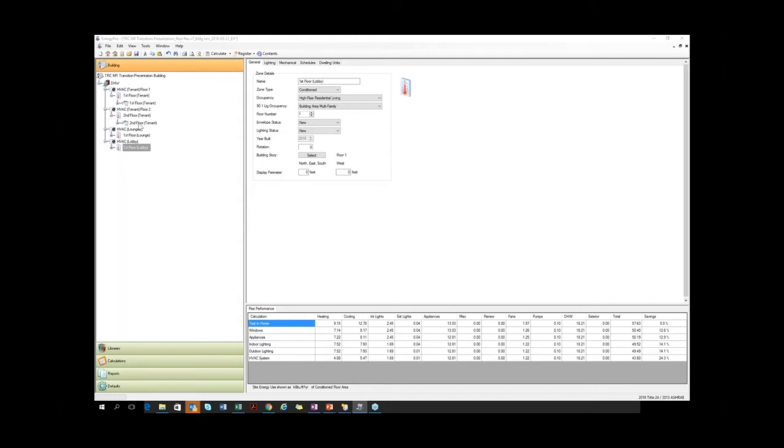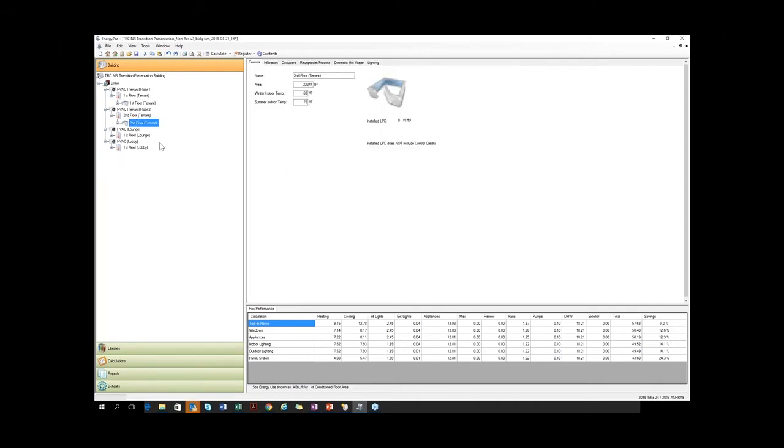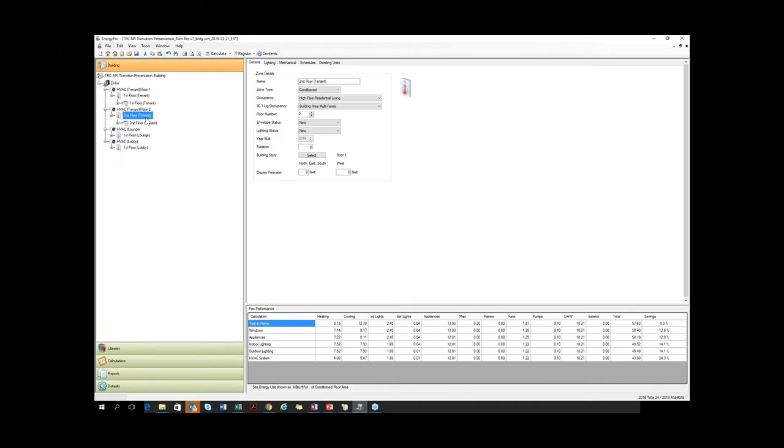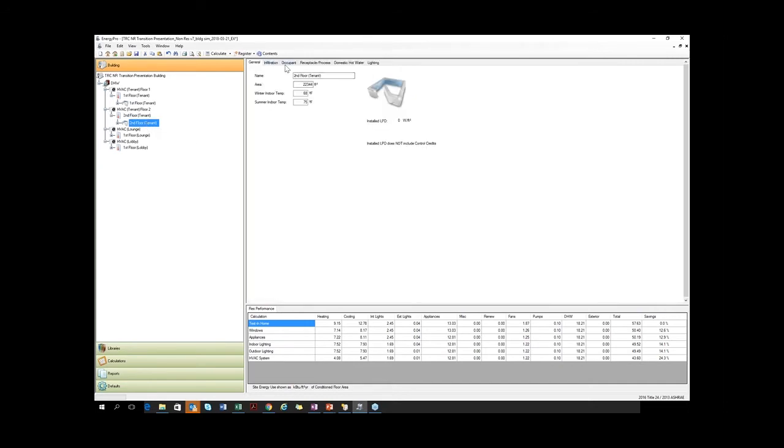So going back to the, so the question is there were some questions about the load assumptions. So basically when you're running a residential calculation, you have some assumptions made about the performance of the building. So you have an assumption about occupant density, sensible heat per occupant, and we don't want to run it with the assumptions of residential. We want to run it with assumptions of high-rise residential or non-res.